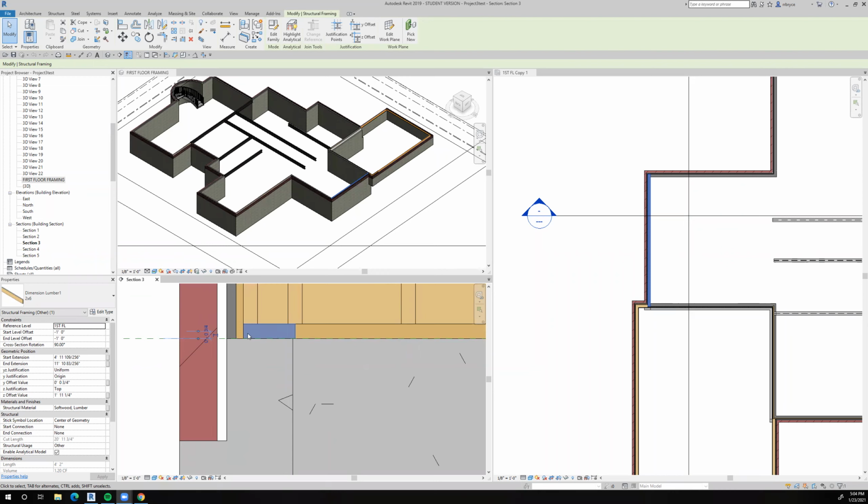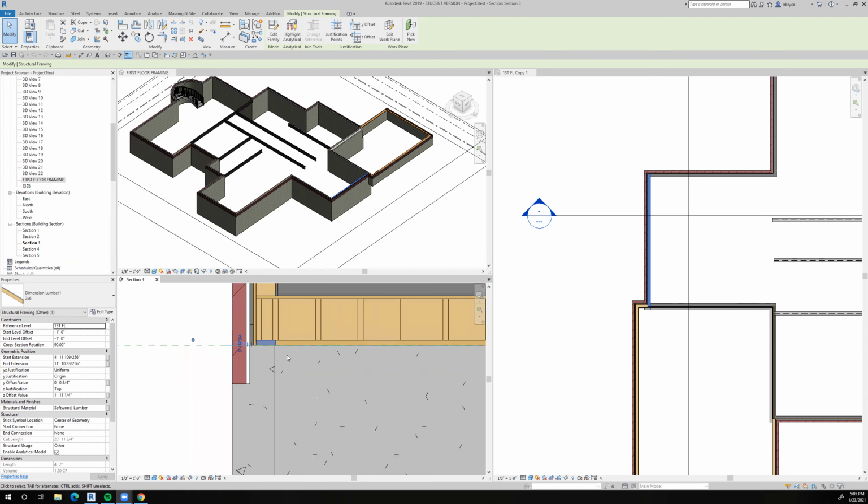We generally put some kind of sill sealer in there as well. It's a fiberglass material, and if there's any cracks, or if the basement wall isn't straight across, it's got a little dip in it somewhere or other, that sill sealer helps to stop the infiltration of air through the house a little bit.